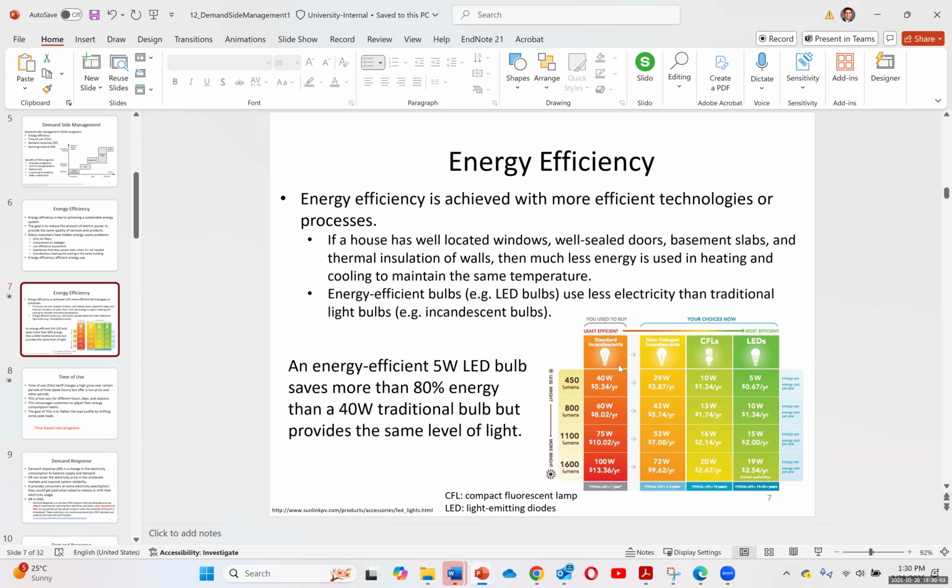So this is a comparison between the standard lights, LEDs, CFLs, and halogen lights. You can see how efficient LEDs are. For the same light output, the incandescent light consumption is 100 watts, LED is 19 watts. So instead of paying $13 per year for electricity, you pay $2.50. So 1/5. And it generates less heat. So if you're in the summer, the incandescent is like a small heater, and the LED lasts much longer.